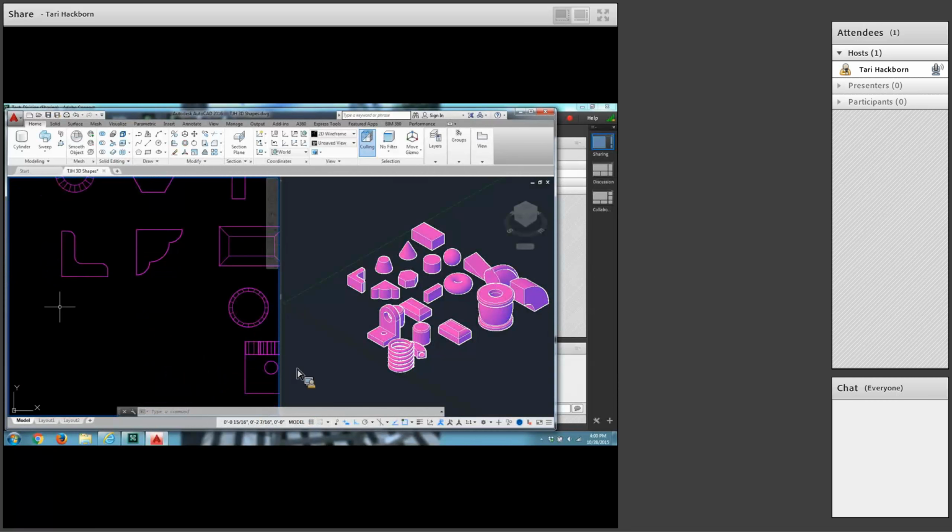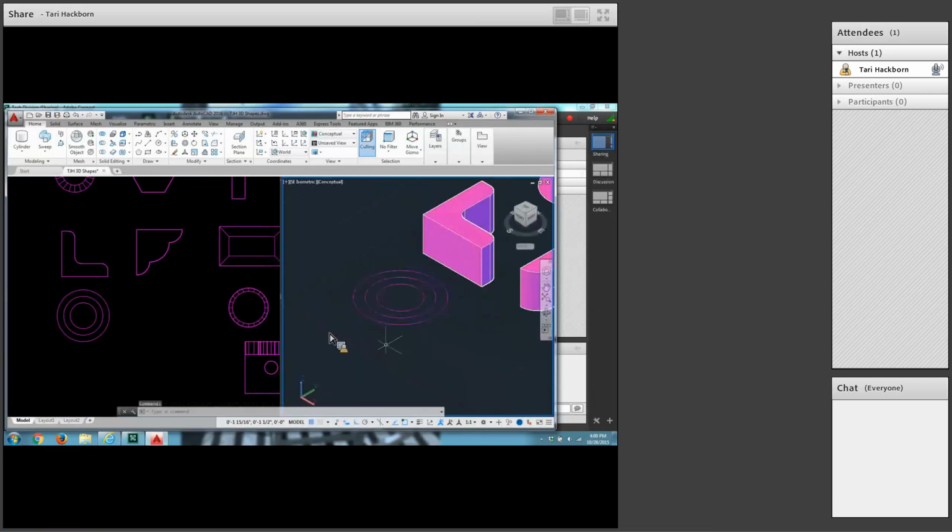Draw 3 circles. Half-inch radius. 3/8 inch radius, concentric circles, so they'll start in the center of that one. 3/8 inch radius, and a 1/4 inch radius. All right, then what? Let's adjust the view now so we can see what's happening. I'm going to make this a little bigger over here so you can see what's happening. Now I'm back on the top view.